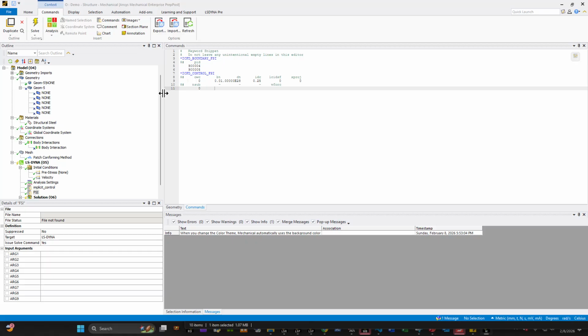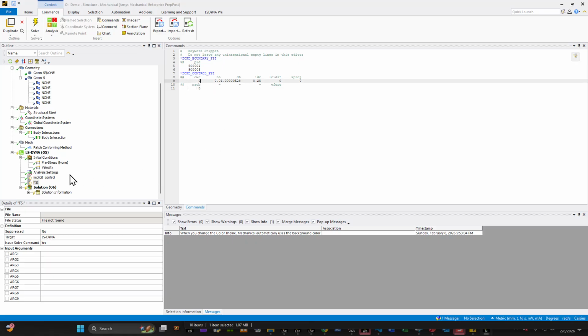And I need to make sure they're in the same location as my mechanical part, which I did because I was doing this inside SolidWorks first. I make sure they overlap each other. And here is how you define the FSI interface. If you set this to 0, you basically have a strongly coupled FSI problem, which requires implicit solvers to initiate. Okay. And believe it or not, that's basically it.